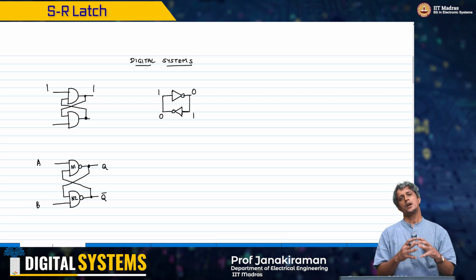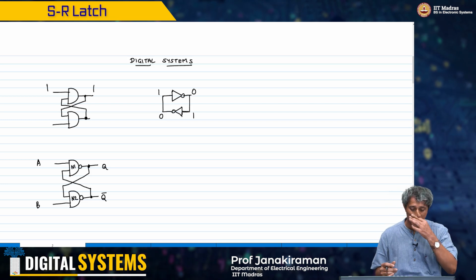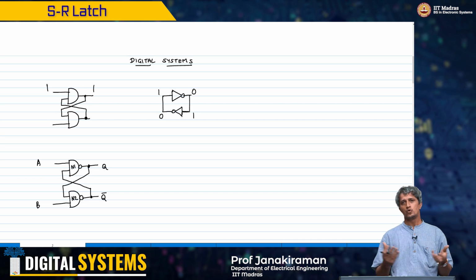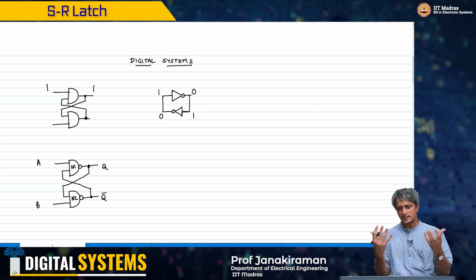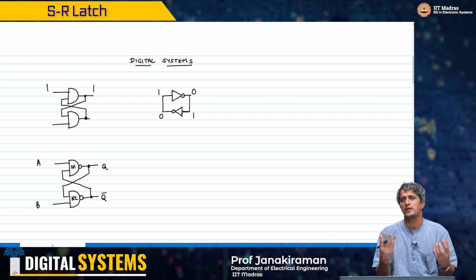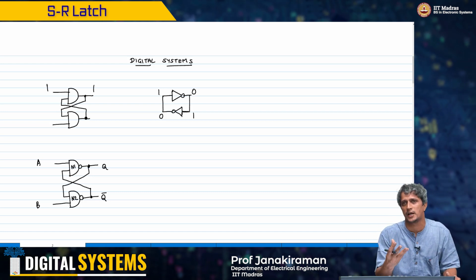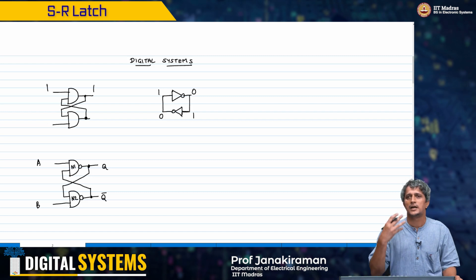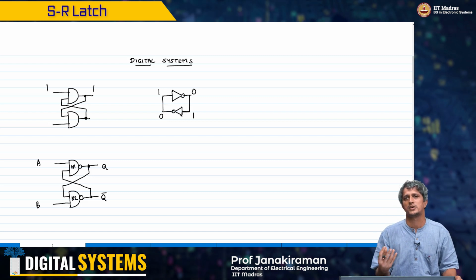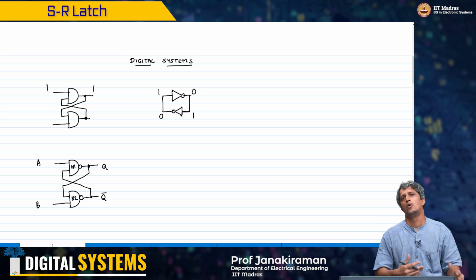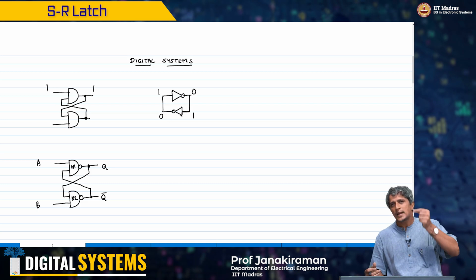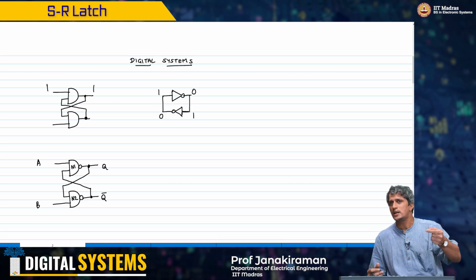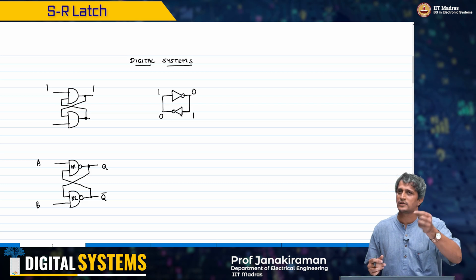So now, in order to analyze this system, we first of all need to identify the configuration in which this structure can hold the data. Remember, ultimately the cross coupled structure is supposed to hold data for you. Now you have two NAND gates with the other input free. When you make the other input 1, the NAND gate behaves like an inverter.